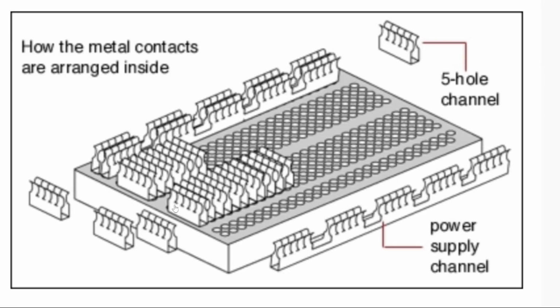As I mentioned here, I showed you these metal strips. They are placed horizontally on the breadboarding area, and on these power strip columns, underneath it's one big metal strip. That's why the entire column is connected, the holes are connected underneath. So you will find one metal strip underneath this column, another metal strip under this column. Similarly, as you can see here, there are two long metal strips for the power connections, ground and positive or negative supply. Okay, so let's go to the next slide.